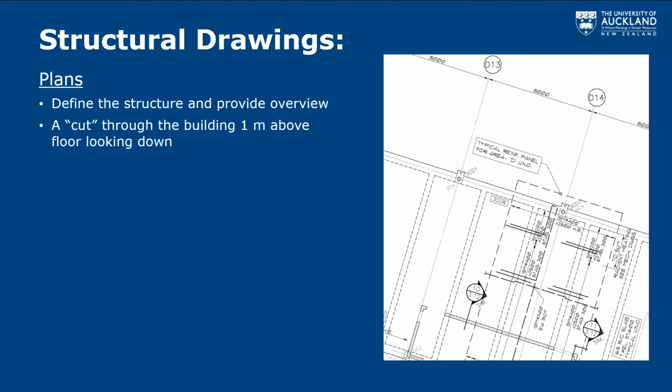And then you'll notice that we've got dimensions and other call-out lines, which are a thinner line weight so that they aren't as visually stimulating, because what we want to make sure is that the structure has the heaviest line weights and is the easiest thing for us to see, because it's the most important part of the drawing.